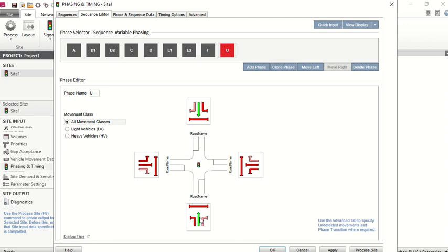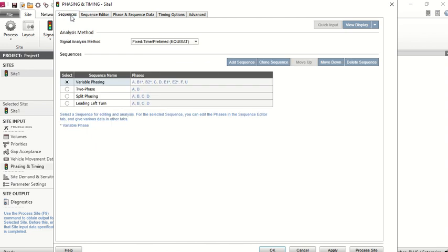Okay, yes. In phase B1, when you block the movement of pedestrian, will they add it to another movement or another phase? It should. If you don't do this, it will show you an error, because it may have already assigned the pedestrian to one of the default phases.